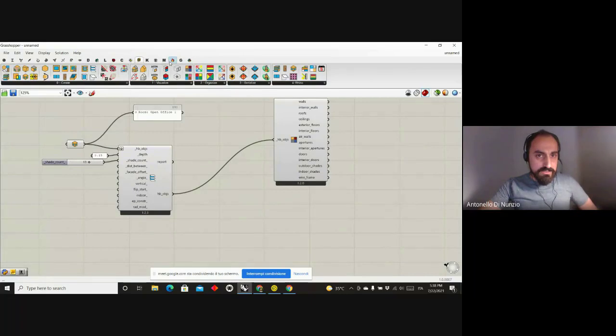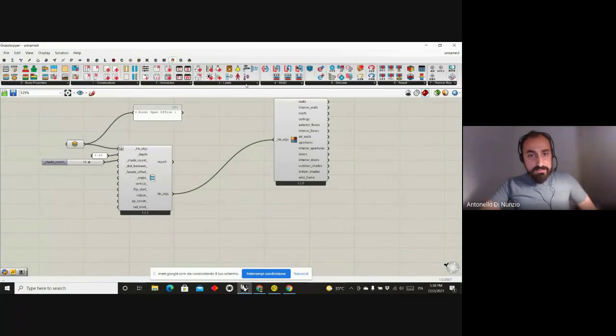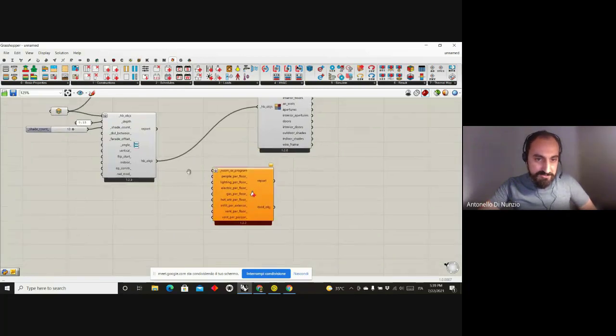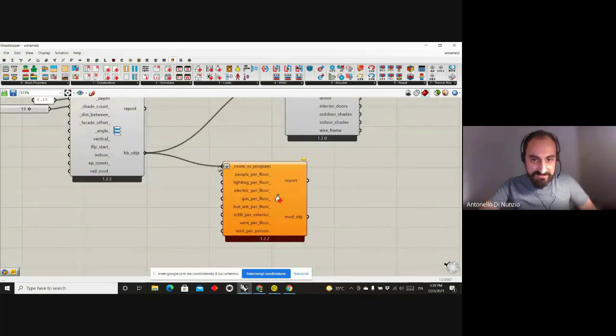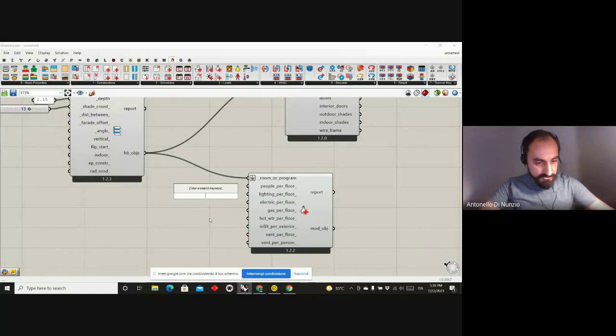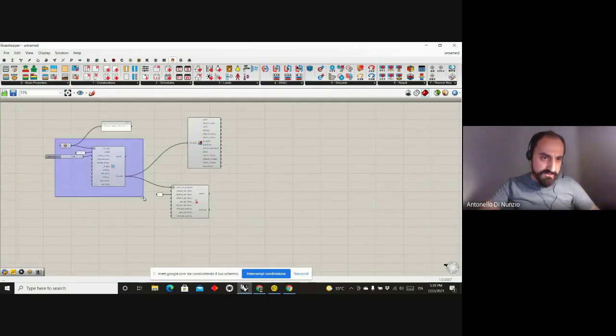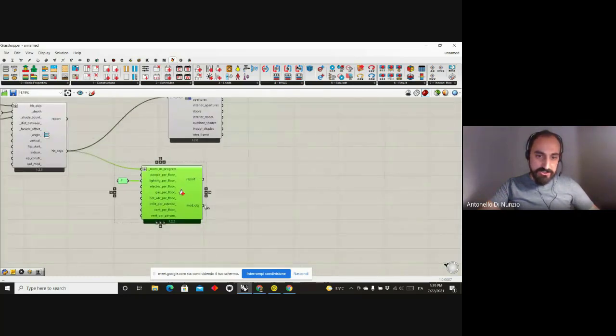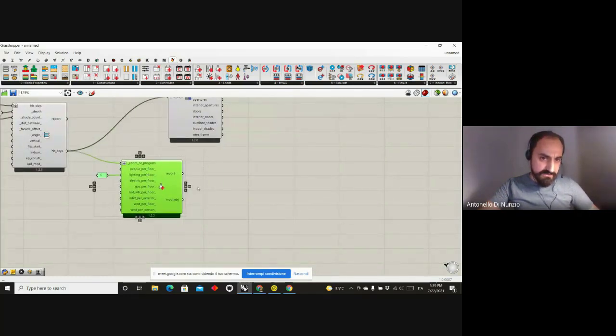So I can use Honeybee Energy, and I can replace the value that I have, for example, with the one from my light designer. Let's suppose that I have some LED inside, and I replace it with 6. So in this part, I replaced part of the geometry. I added some louver shades. In this part here, I'm changing the lighting system.